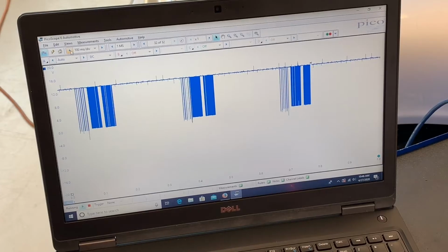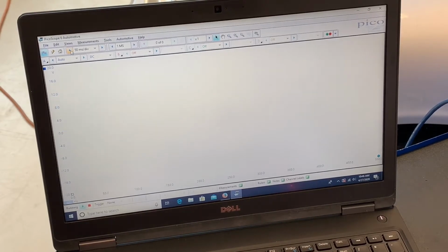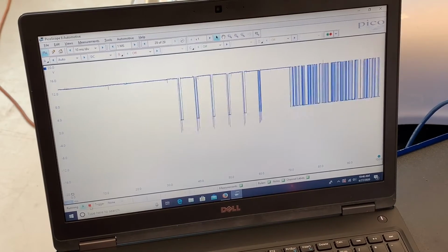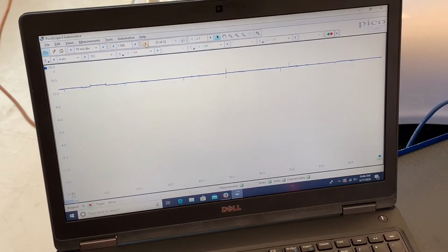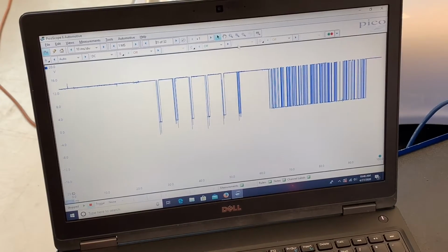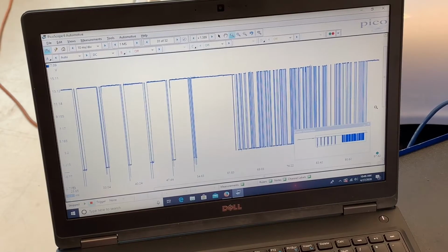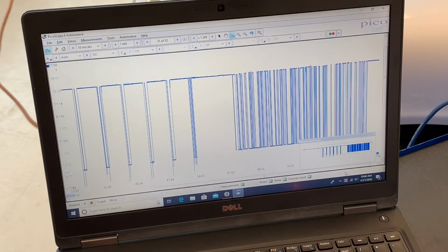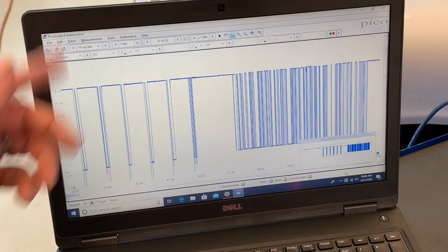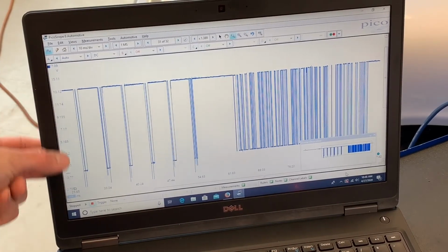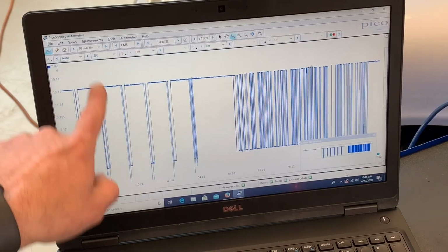Anytime we have information that's transmitted within a serial system, or really any electronic data system like this, we refer to those as packets. If we pause this, I'm going to go back a frame or two until we get one of the packets, and we'll take a closer look. This packet is digital communication. Because it's digital, the only changes I've got in this waveform are on-offs. I'm going from 13 volts down to 0. This is a full source voltage just switched on and off.